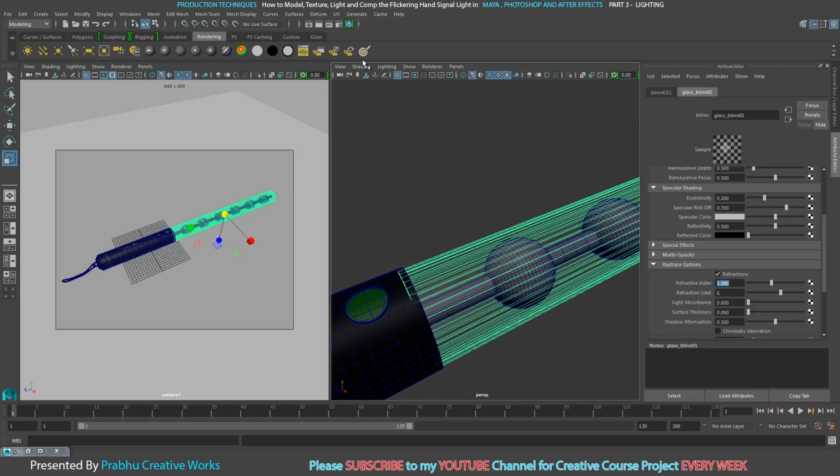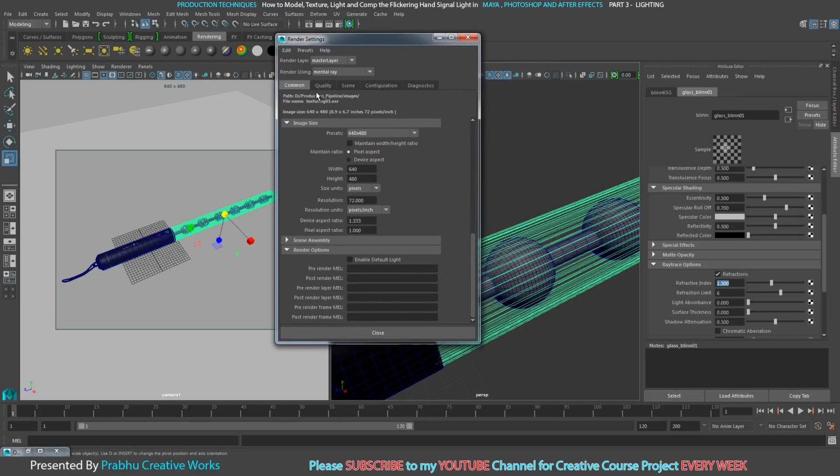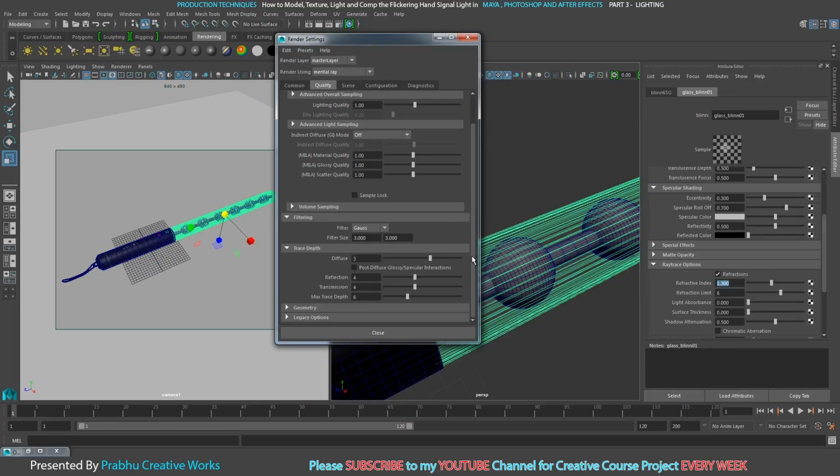So I want that. Go to render settings. You want to enable it in the render also. Go to the quality tab. So you want to turn on show advanced settings. Here we have the trace depth option. So go over here. Here we have reflection, transmission, and maximum trace depth. So I will explain what these are. In this case I have one reflection, one transmission, and maximum trace depth 2.